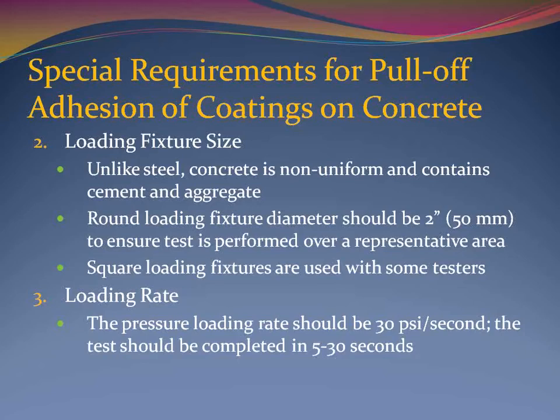The third requirement is regarding loading rate. The loading rate applied to the fixture by the adhesion tester should be approximately 30 psi per second so that the test pull is complete in 5 to 30 seconds.